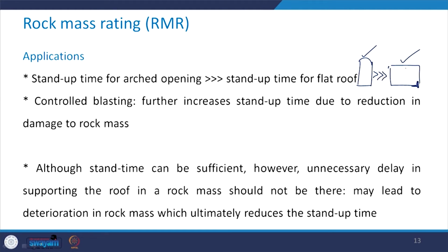Now, if for the excavation purpose you are going for controlled blasting, that further enhances the stand up time, because when we go for controlled blasting, there is going to be a reduction in the damage to the rock mass and therefore the stand up time increases. You have seen that stand up time can be as large as 20 years for a 15 meter span of the tunnel in case of a very good quality rock mass.